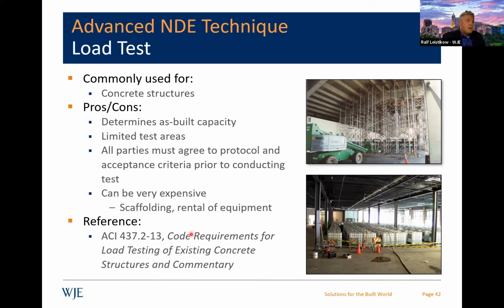One of the things is, these can be super costly, potentially, depending on the scale of them. And obviously there's a chance of damage. It's important up front to make sure all the parties agree on the acceptance criteria. When does a test fail or pass? That's pretty important to do up front. And you have to add scaffolding, as you can see here, and rent other equipment. So it's not simple, but sometimes that's the only solution to resolve some kind of question about structural capacity.